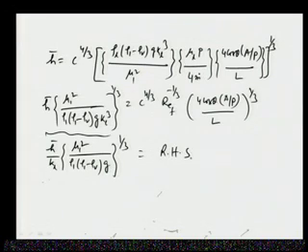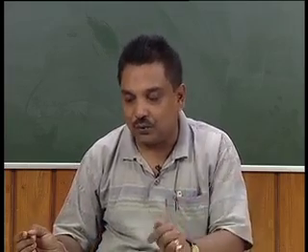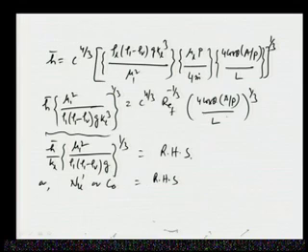So, we can see the left hand side is nothing but Nu dashed, or the condensation number, and that is equal to the right hand side. In the right hand side, what we find is a combination of a coefficient, that is the constant term, a flow parameter, that is the Reynolds number, and a geometrical parameter, that is 4 cos theta A by P into L divided by L. This whole part is a geometric parameter, this is a flow parameter, and the other one is the constant term.